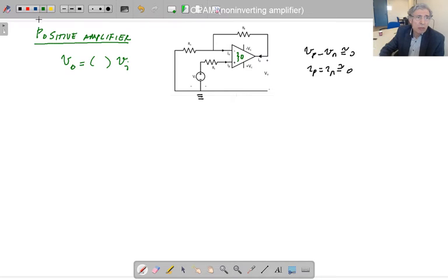As we have done previously, we are going to write a Kirchhoff current law equation for this node, just one node, so one equation. We need to choose the element current references in order to write it. I have chosen these references like that. If you choose them the other way around, the results do not change.